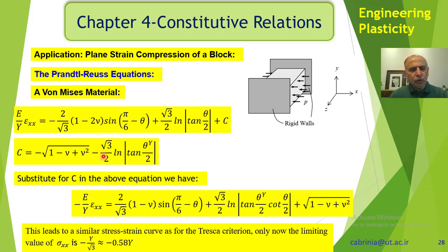But at the yield point, it yields and it will not come back to its original position. Now after the yield point, what happens there? That's where the flow rule comes in, like these Prandtl-Reuss equations and other equations, so that they show how it changes.